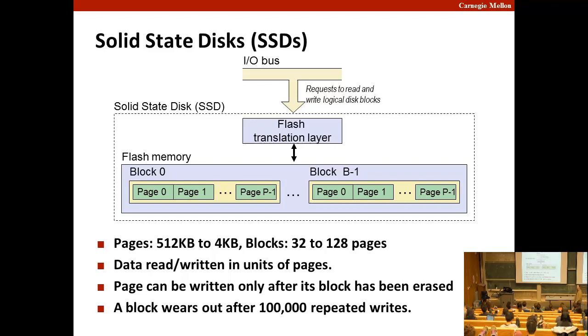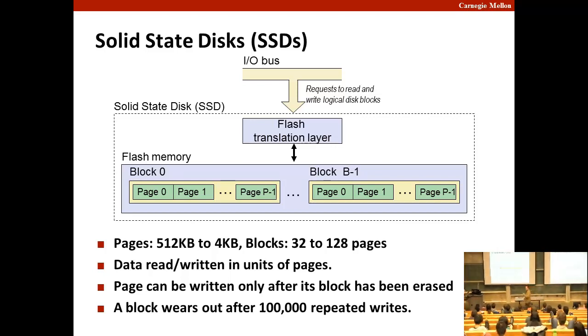And so it's able to do things like wear leveling. Like every time we write, swap in a different block so we don't keep using the same block over and over again. If one goes bad, replace it with another and hide that from us. Okay? That's called the flash translation layer. And so we have the flash memory and the flash translation layer together form some solid-state device. These can be small things like thumb drives or big things like SSD disks.